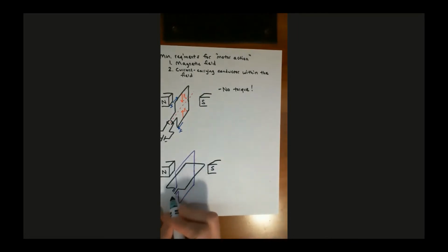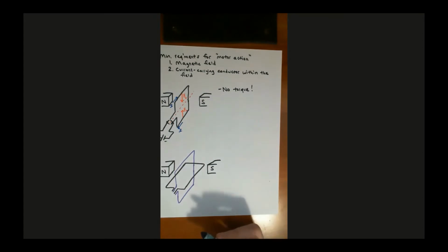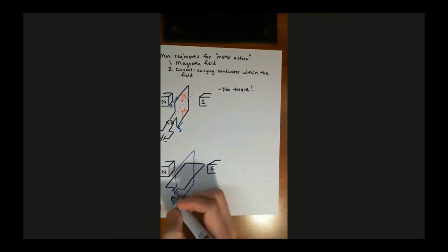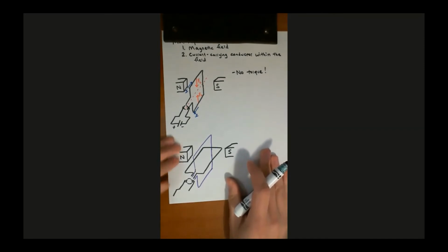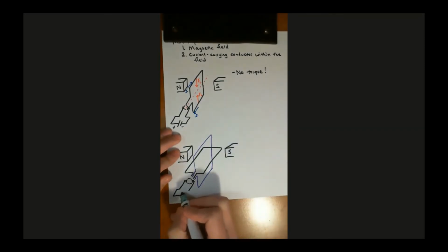And then I'm not going to try to draw this, but what you can see, you've got 4 different wires coming in, 2 wires from each coil on the armature. So our split ring commutator is going to have 4 segments like that. We've still only got 2 brushes. There's a brush, and there's a brush. And the brushes are connected to the DC power supply. I don't know if you can see that.